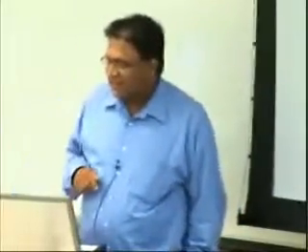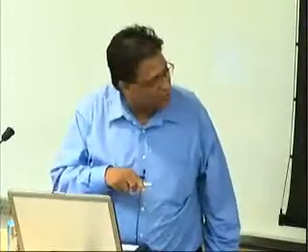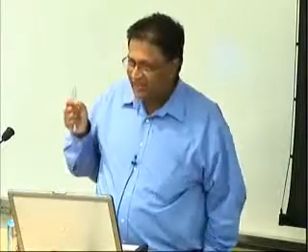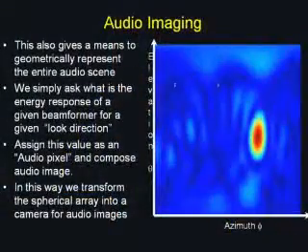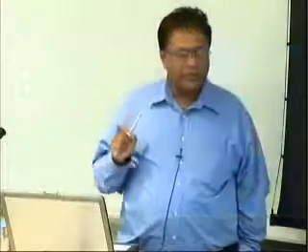Quick question. Besides the main image, those light blue spots, what are they? Are those the side lobes, or actual reflections? Those are actual reflections. There will be some side lobe contamination also, but the side lobes are relatively weak in this array. It is like the point spread function of a camera; there will be some spreading, but most of these you can reason are actually reflections. The lower part is reflection from the floor, the upper from the ceiling, and those are from the walls. Wow. So we essentially transform the spherical array into a camera for sound.